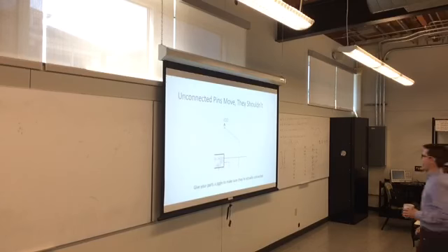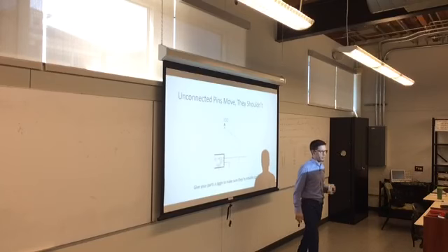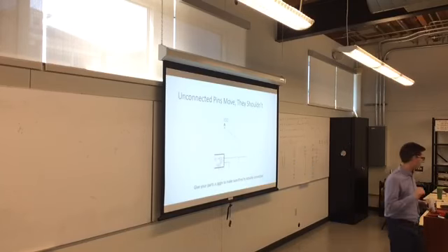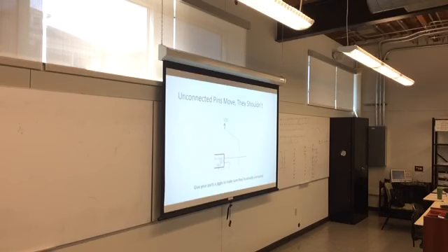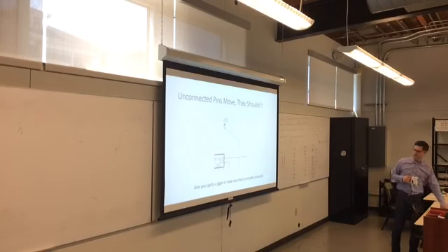If lines are actually connected, there needs to be a junction here. So one trick is, once you've wired up all of your schematics, grab a part in the schematic and just jiggle it, and make sure that all of the parts and all the nets move with you. If it moves free of some of the nets, then that means they're not actually connected.